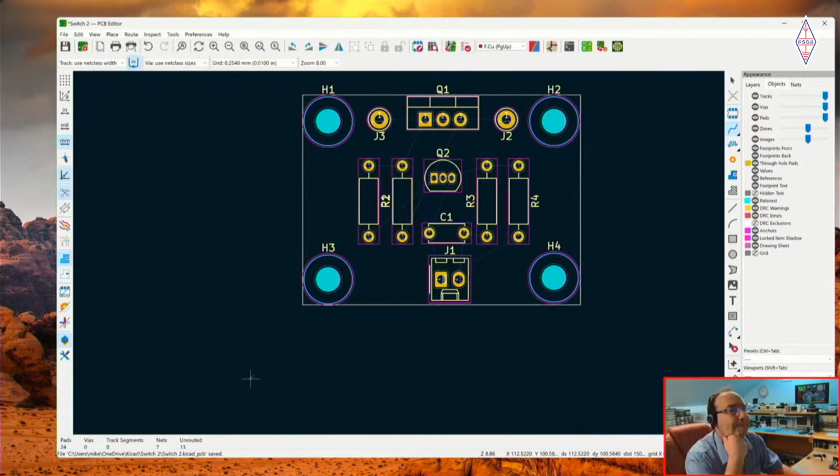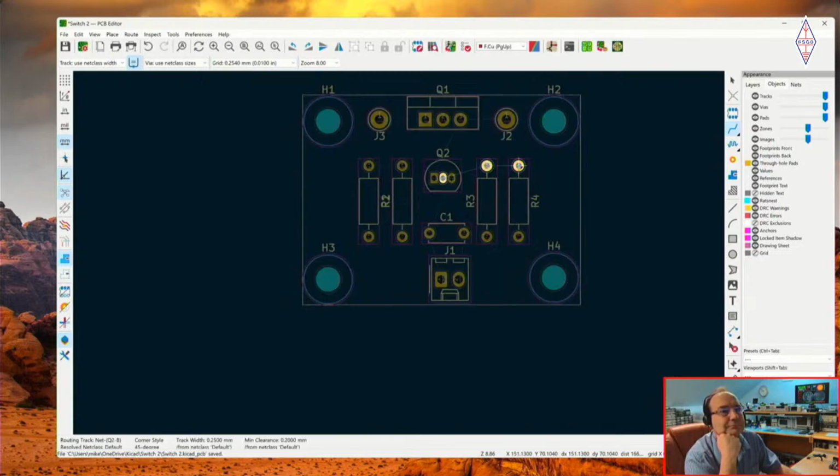And again, if you don't mind me, just for the sake of those really beginning in this sort of thing and maybe never considered a circuit board, some printed circuit boards are single-sided, which just means that there's copper on one side. There's no copper through the holes and there's none on the top side. But as Mike said, this particular board is going to have 2 sides. There's copper clad, as it's called, both sides of the circuit board, and we're going to use both those sides.